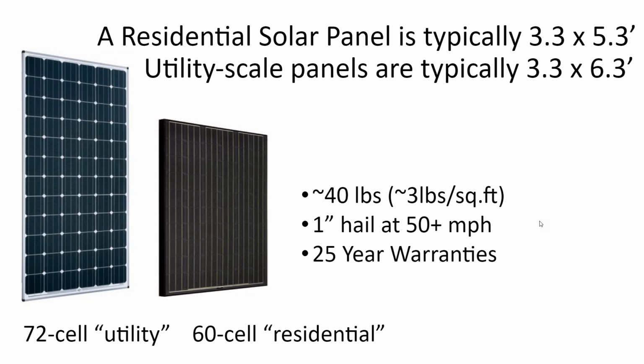The solar panel, again, thinking about what one worker could pick up on a rooftop, they weigh about 40 pounds. It's not a terrible idea to use 2 people to carry them on the rooftop. Generally, if you're passing them up a slanted roof, you're really not trying to walk around on a rooftop too much to begin with. Manufacturers know that this is outdoor rated electrical equipment, so they are rating it to take hail damage. It's rated for 1-inch hail at 50 miles an hour.